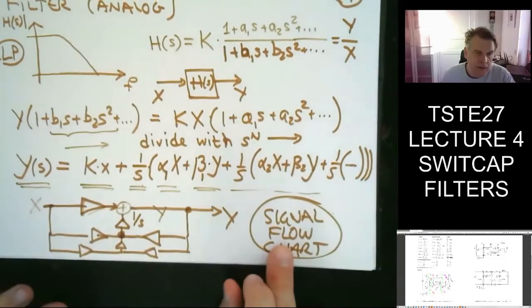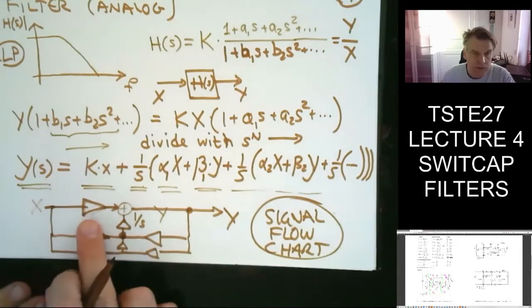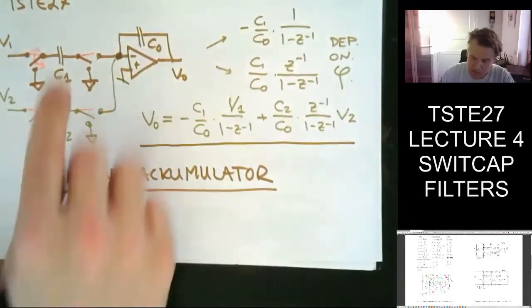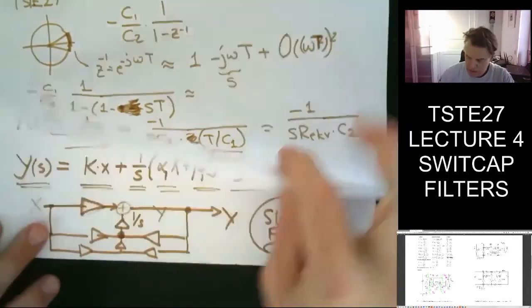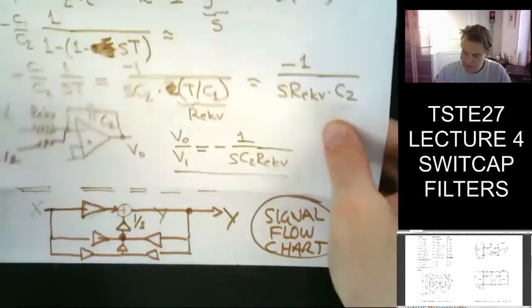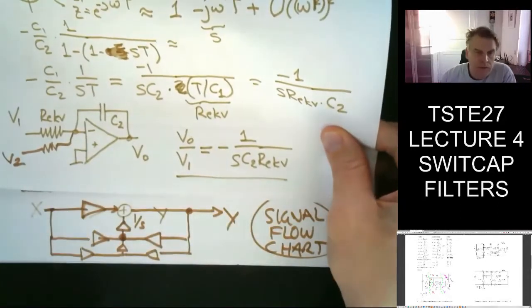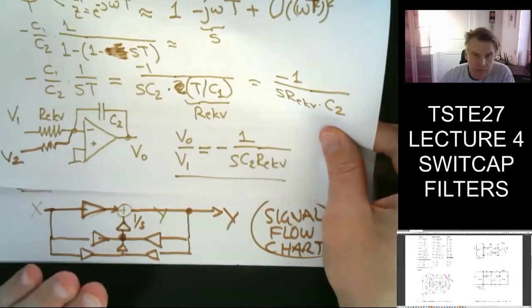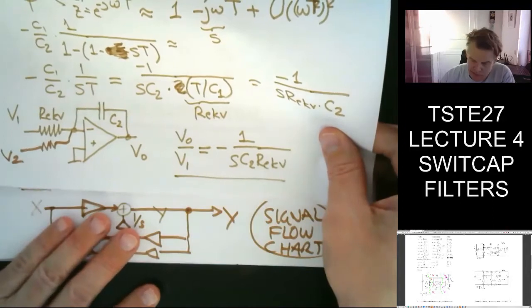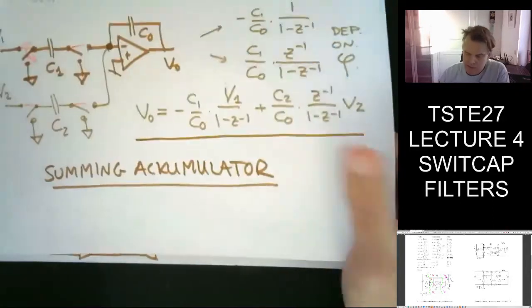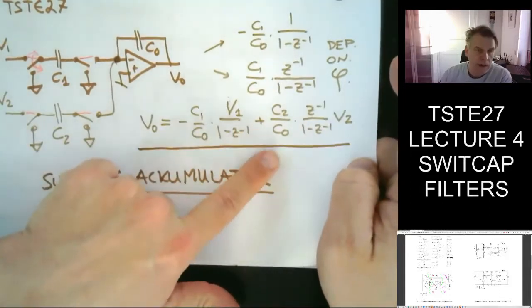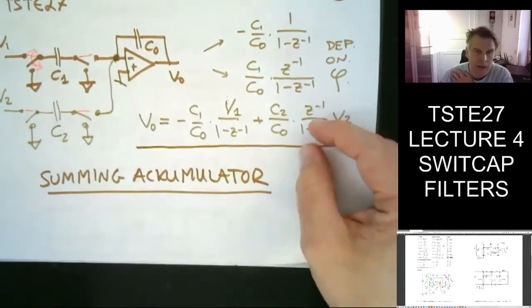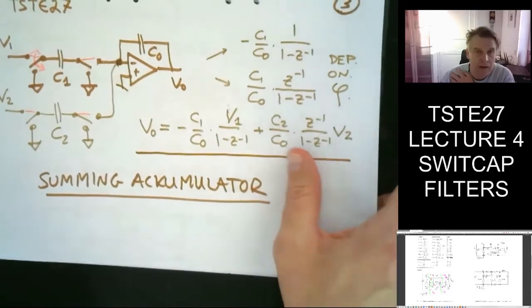That signal flow chart is quite easy, because we just replace the summations and integrators that we have, like this. So we can then realize this flow chart. And once we have the flow chart in place, we just replace it with our summing, inverting, and gain amplifying accumulator.